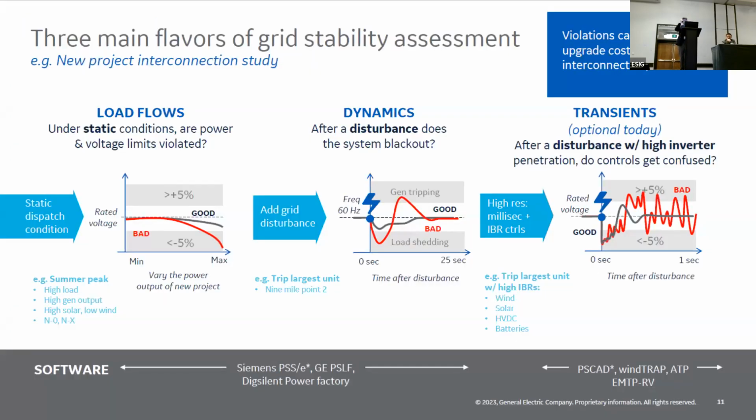And then another slide on the different types of load flows, on what I would call the technical side. So you have a load flow analysis, where you're really looking at the voltage on the power system, the dynamics, and then also the transient stability on the system.